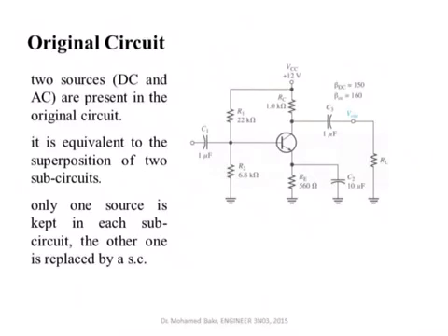Similar to the case with MOSFETs and JFETs, we have two types of signals. We have a DC current flowing in the circuit, and we have an AC current or AC voltage being imposed from the AC source. Then we can do two types of analyses: apply superposition and separate these two. First, we do the DC part, determine the DC currents everywhere, and when we do that, we consider all these capacitors to be open circuit. And then we do a second analysis, the AC analysis, where we consider these coupling capacitors to be short circuit,